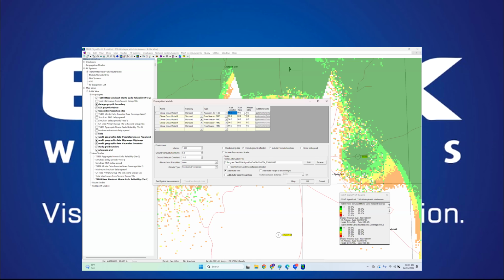So typically, if we are using studies that include fading as part of the study result, then we would set up the propagation model to target the average signal level that we're actually measuring in the field.